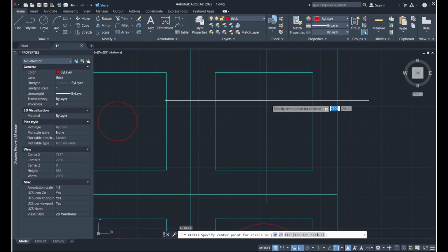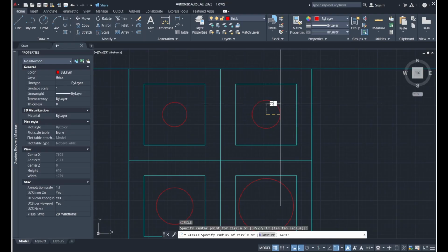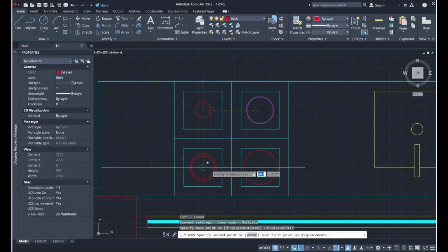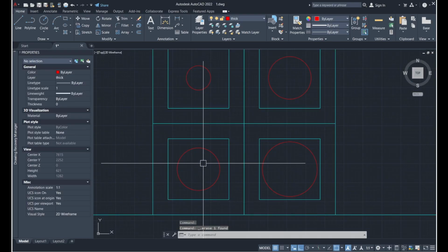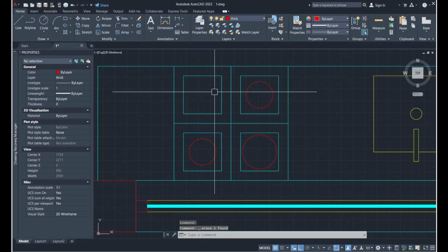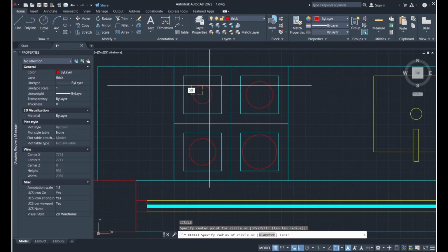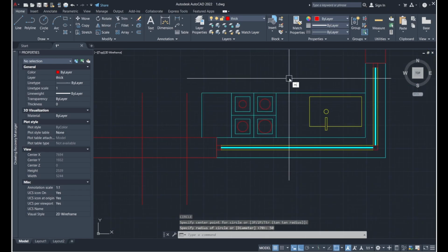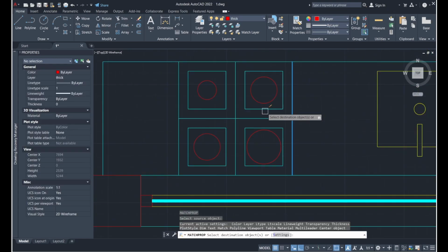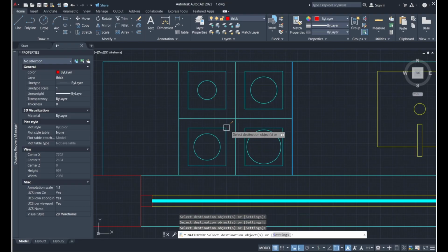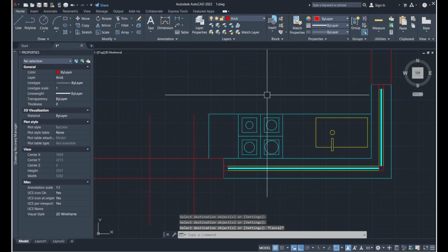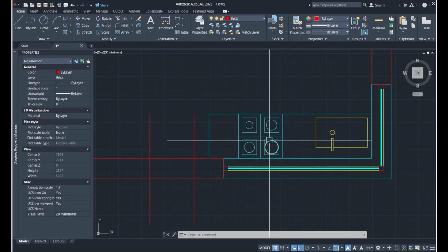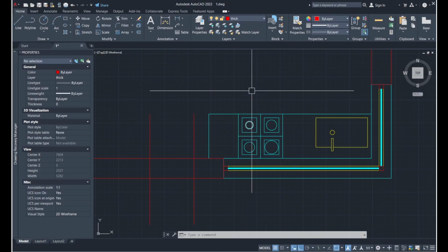Let's delete this, draw again, make this 70. Let's copy this over here, delete this one, and let's make this one a radius of 50. Yeah, so we have drawn our stove. Let's just match properties. It's like a 4-burner stove with one of them for a really large pot and one for like a teapot or a kettle.